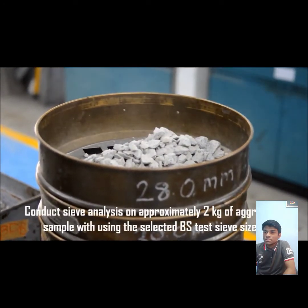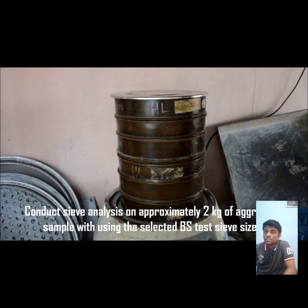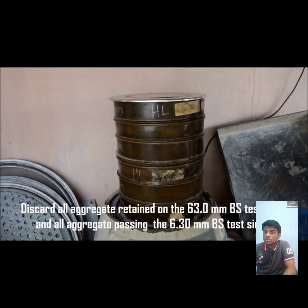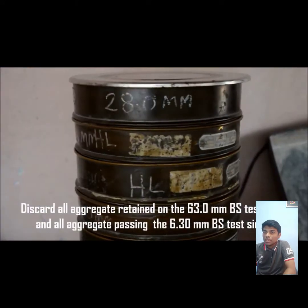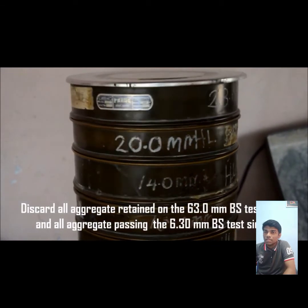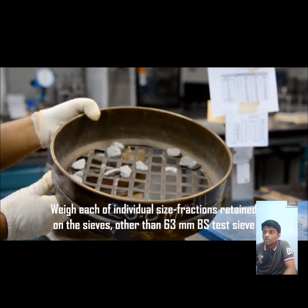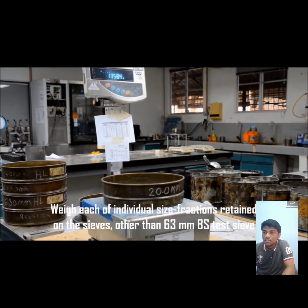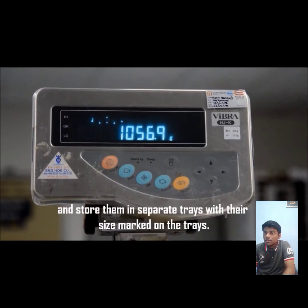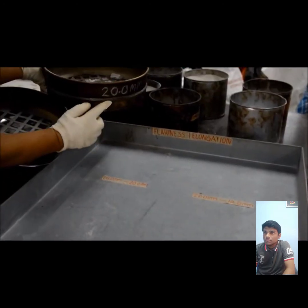Conduct sieve analysis on a 2 kg aggregate sample using the selected BS test sieve sizes. Discard all aggregate retained on the 63.0 mm BS sieve and aggregate passing the 6.30 mm BS test sieve. Weigh each individual size retained on and above the 6.30 mm BS test sieve and store in a separate tray with the size marked on the tray.